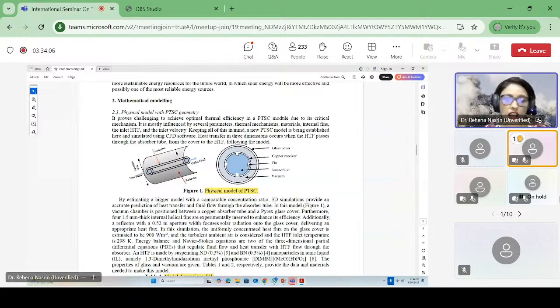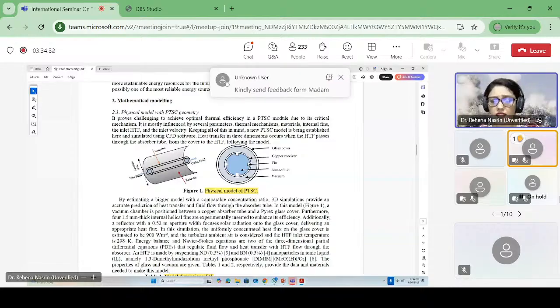The reflector gets the radiation, and from all sides of the reflector, it concentrates onto the absorber pipes. So the backside of the absorber pipe becomes more hot, and then if we flow inlet fluid, cold fluid, we get the outlet fluid as hot fluid.